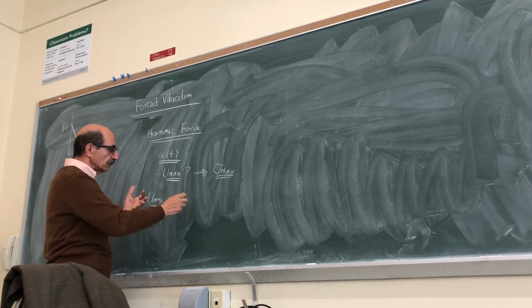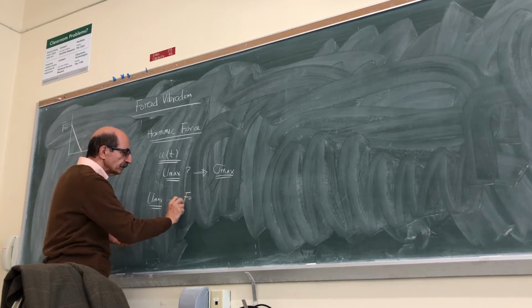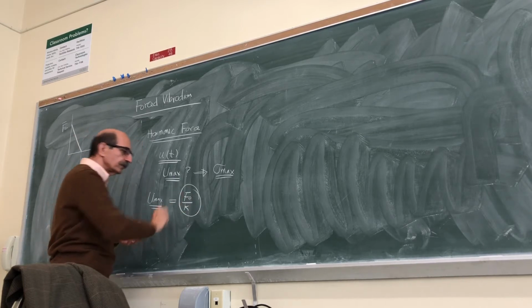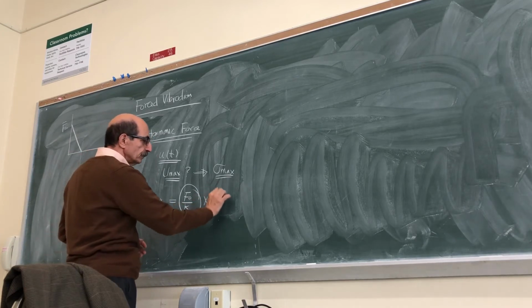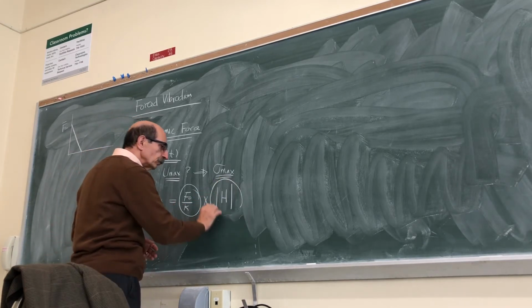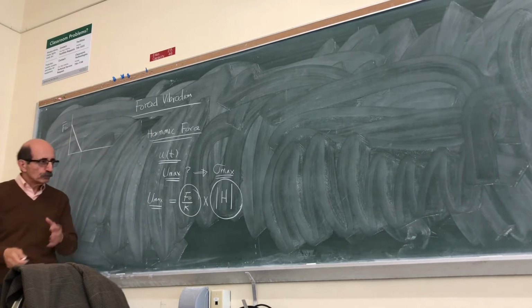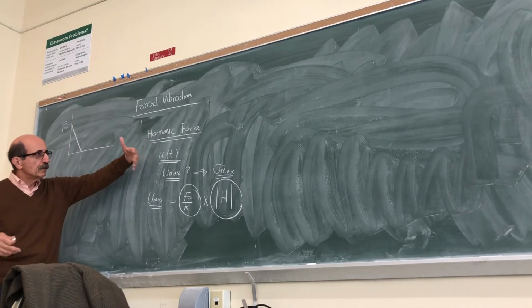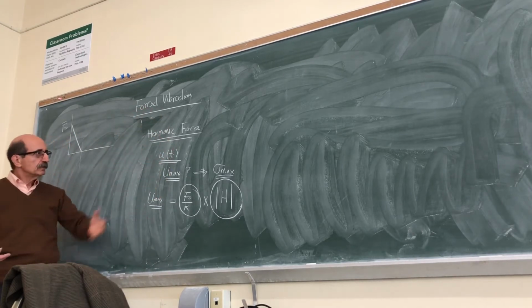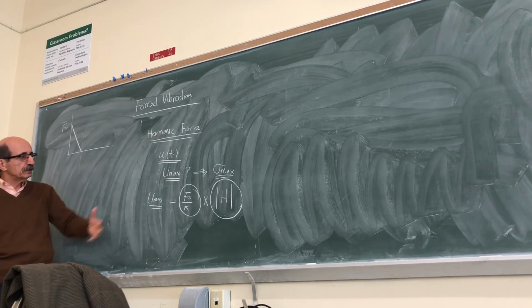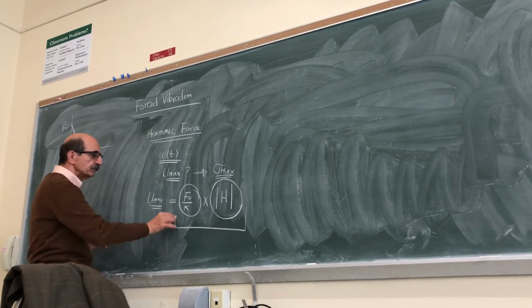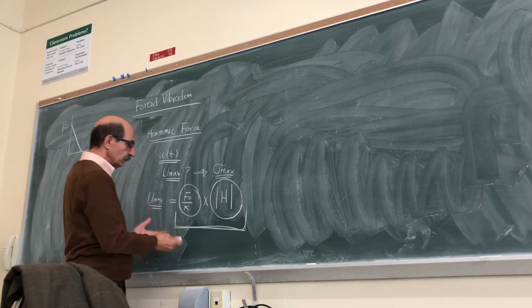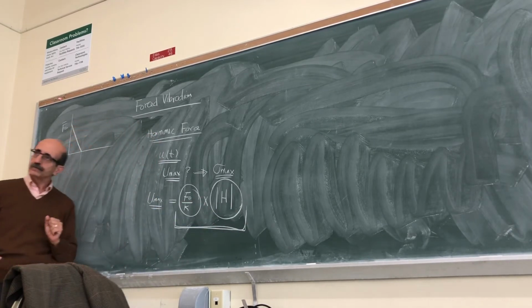It came down to having the static displacement times the maximum value of the frequency response function. So no matter what the frequency or the amplitude of that forcing function is, we have a relatively straightforward way to find the maximum displacement.